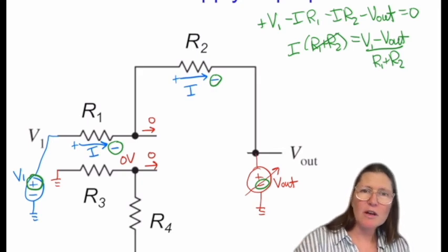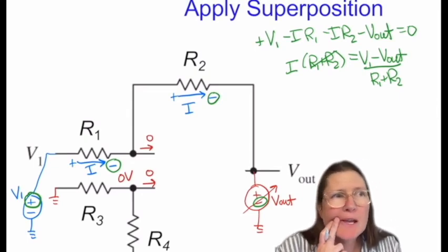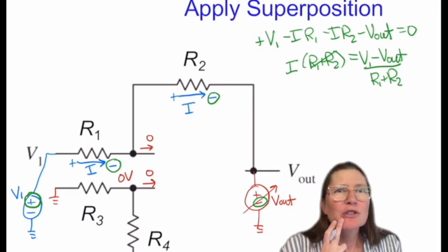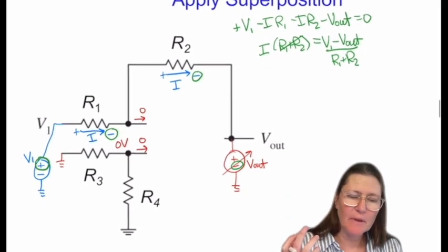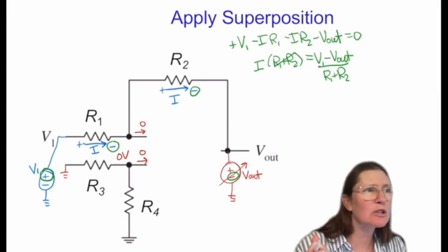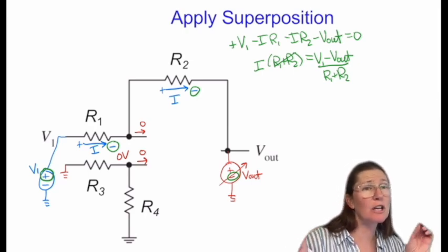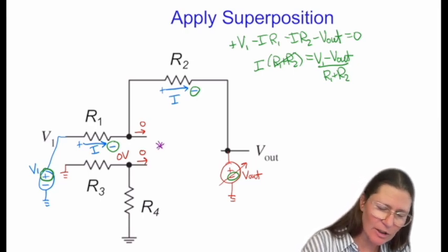So we have two unknowns here, right? So how do we get the other equation for this one? The other thing with an op-amp when you're solving it, which is due to the characteristic of it, and this is key on how to solve it, is that the V negative is equal to the V positive.